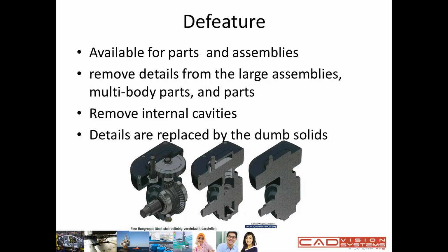Basically, this tool is often used to share files without revealing all the design details of the model. Another benefit is that the simplified model can improve performance by simplifying the graphics and model information, and also reduce the review time. Once you apply the defeature, in the new file you will get the same mass and the same center of gravity as assigned when you assign the mass properties.